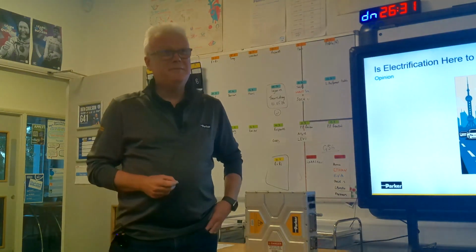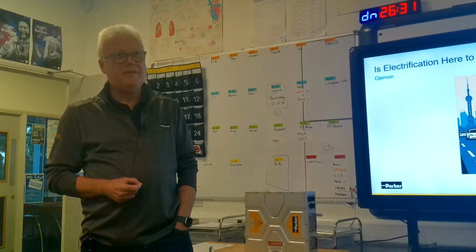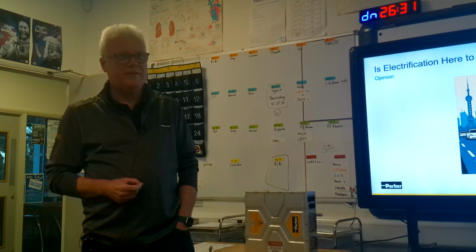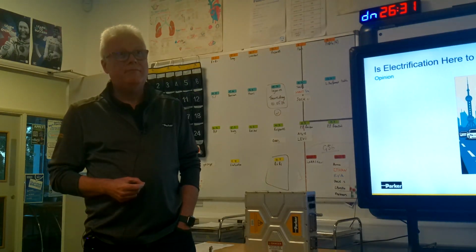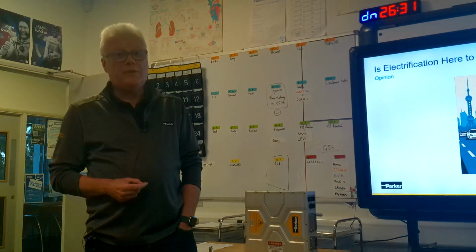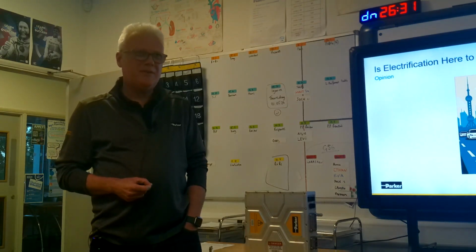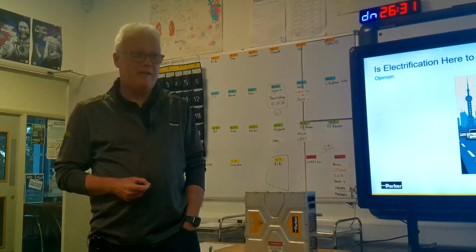But you mentioned 4 to 8 kilohertz for that inverter, whereas the inverters for these kinds of cars have got to go from about 1 hertz to 30,000 or whatever is equivalent. We have a rule of thumb which says I need at least 6 PWM cycles per electrical rev.